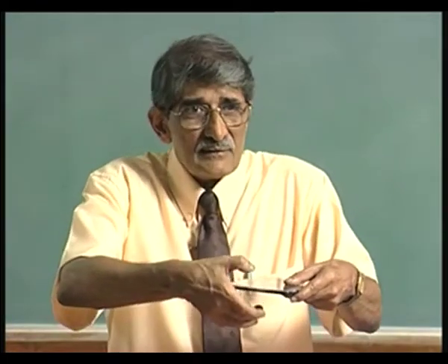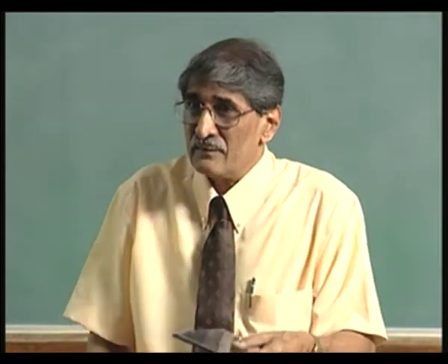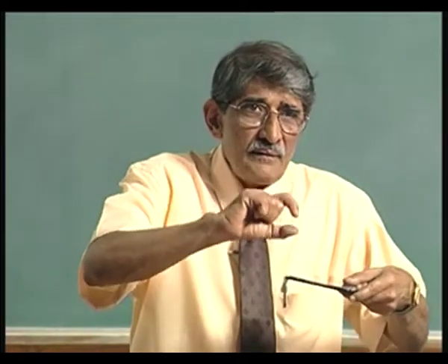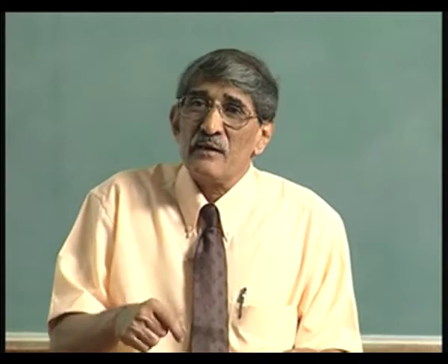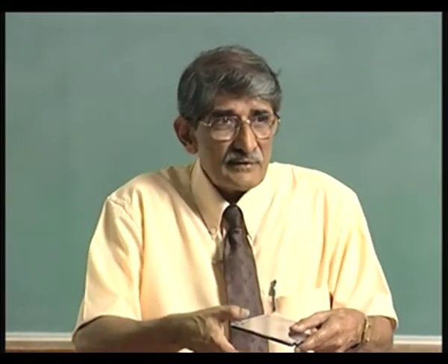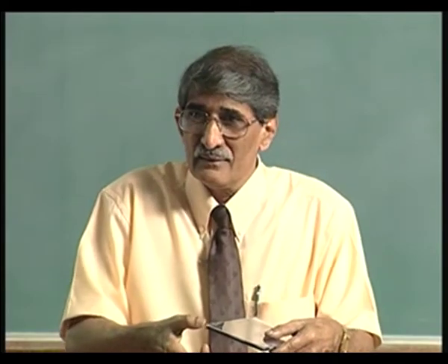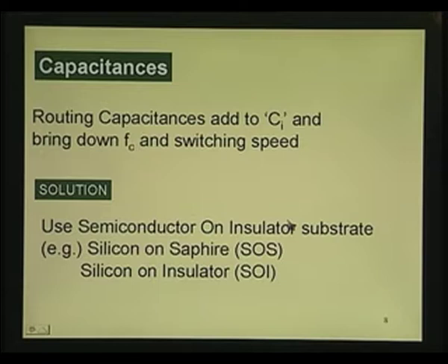So, thickness is more because that insulating layer is present. That is why the capacitance is small. Plus, for the silicon layer you will have epsilon r, which is 12. If it is an insulating layer, where epsilon r is smaller, like oxide, then the capacitance is automatically small. So, what I am trying to point out is, we will have occasion to discuss more about this later.